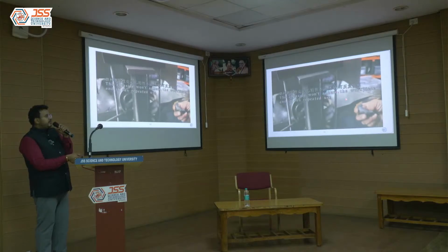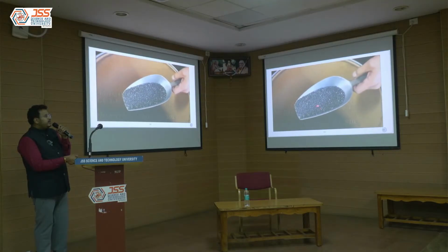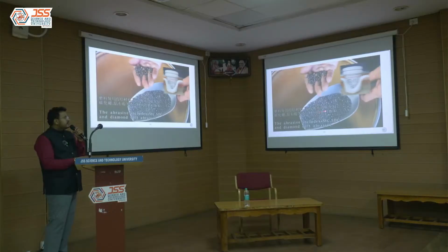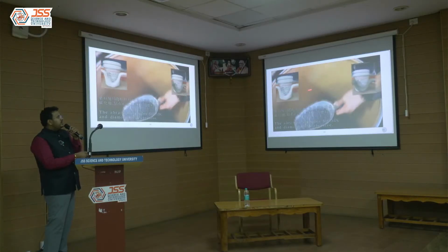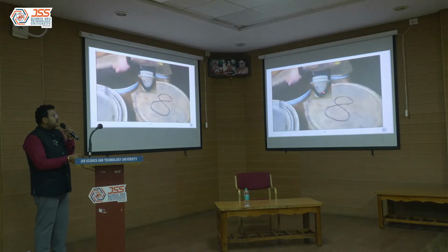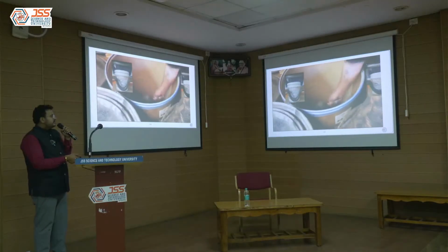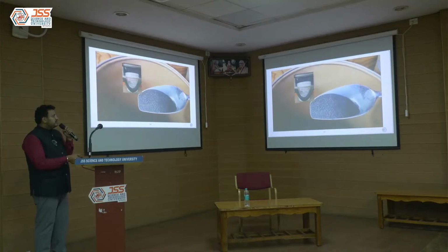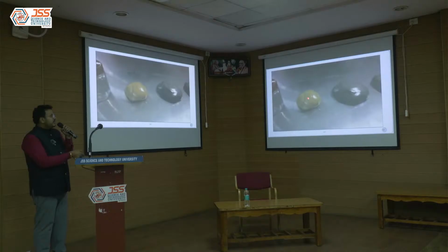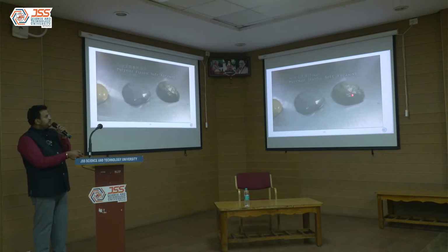And this is the semi-solid media. It is a mixture of abrasive particles mixed with polymer gel. It looks like this, the polymer gel mixed with abrasive. So different grades of abrasives can be used. Yeah. So this is the flexible tool. This is a flexible tool we are using.